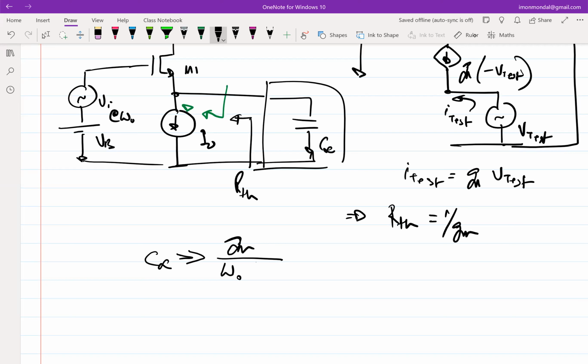What is low first? So what happens at lower frequency? Does the capacitor behave like a short or does it behave like an open? Lower frequencies, open, right? We want this constant is for the capacitor to behave like a short circuit. So if it's a short circuit at, let's say, 1 megaradian, then it will be a better short circuit at lower frequency or a worse short circuit? It will be worse, right? I mean, lower frequency goes towards the open circuit, right? So essentially, this will work properly for higher frequencies.